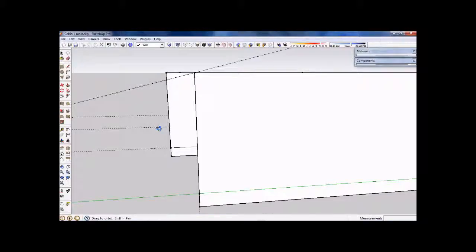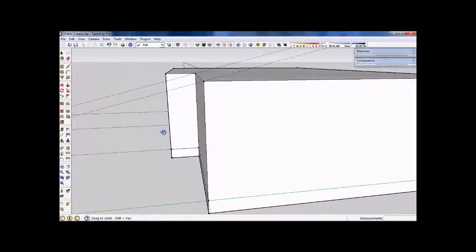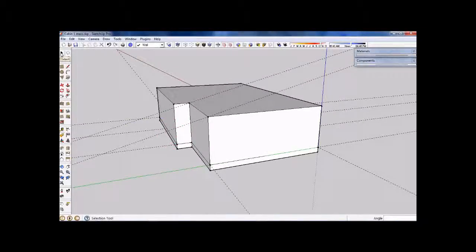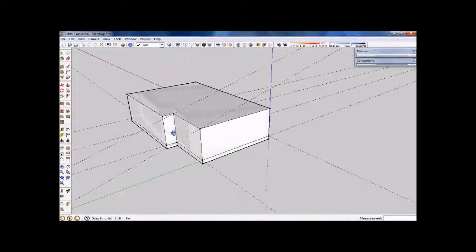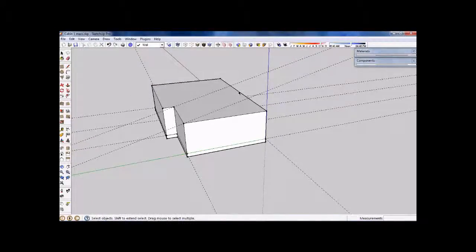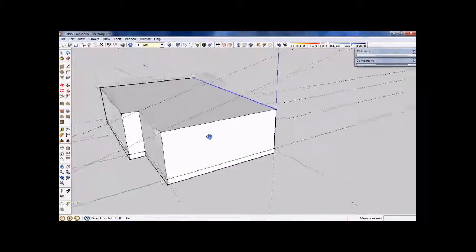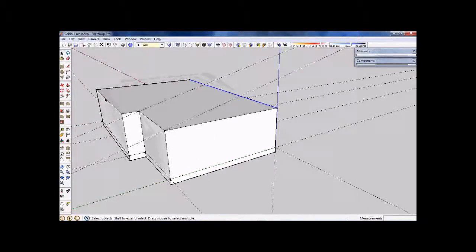And you can see, if you orbit round, in elevation view those two construction lines line up perfectly. Okay, so just go back to your select tool at the moment, because temporarily I need to move this edge here. I need to move it up so that the roof will slope down at that 15-degree slope, and I need to also move this edge here at the back of the pop out. I need to move that edge down so that it will be a 15-degree slope as well.